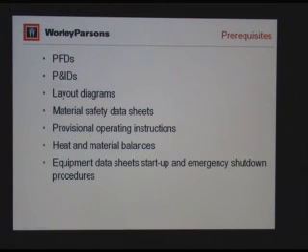And what we're analyzing is any deviations from our design intention and the consequences from that deviation. And the next one is equipment data sheets, startup, and emergency shutdown procedures, and see if they adequately describe what needs to be done during startup and equipment shutdown.